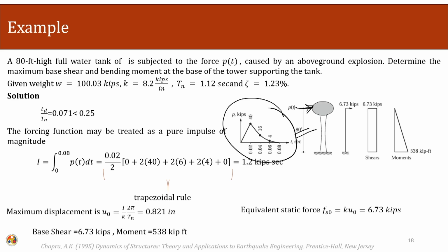This loading we can approximate as being caused by an above ground explosion. Let us say the explosion is acting out here, and this is the signature of my loading. What we need to do is calculate the maximum base shear and bending moment at the base of the tower supporting the tank.